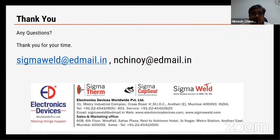Mr. Shashi Shekhar Kumar is asking, is auto TIG good for higher thicknesses? Yes, Shashiji, you can use TIG for higher thicknesses as well. We have done up to about 150 millimeter thick vessels also in auto TIG.